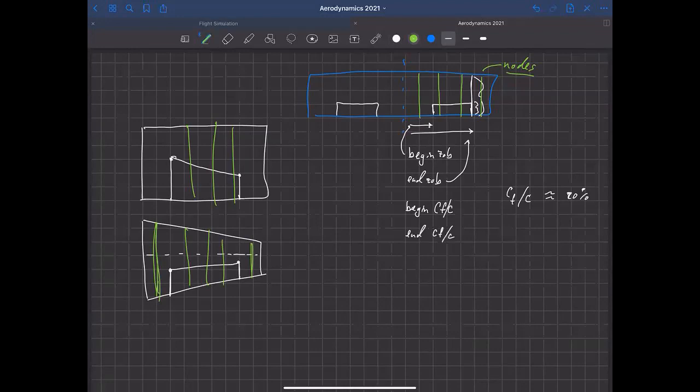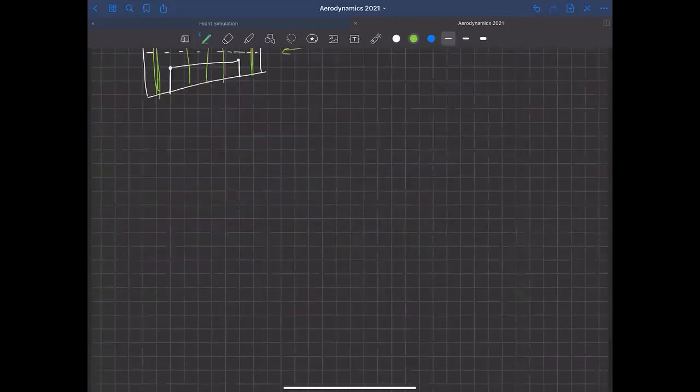Okay, so the tricky part here is that linear interpolation only works if we're working with a rectangular wing or a tapered wing where the planform is changing linearly. In general, and the example problem that you're asked to look at is an elliptic wing.